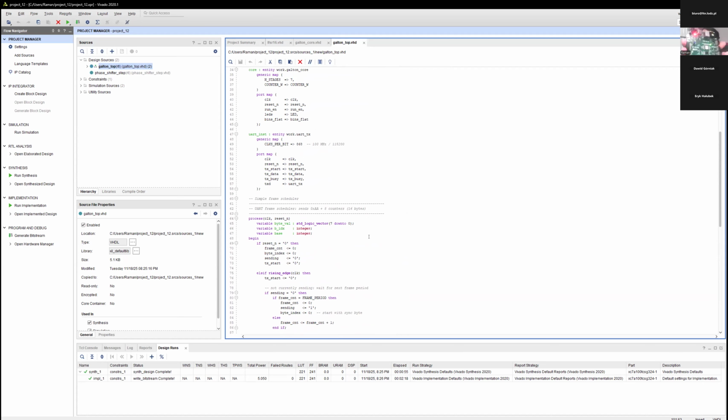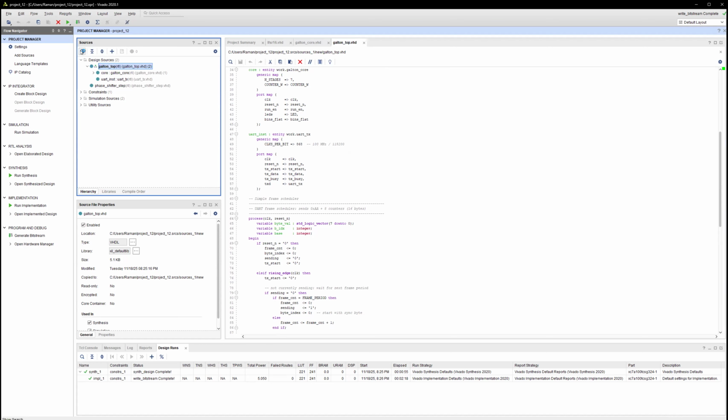If you see right here, I don't know if that's clear, the power port and the UART communication port are the same. In some other FPGAs that you may want to try in the future, that may not be the case. In that case, you'll need another wire or another port to connect them.